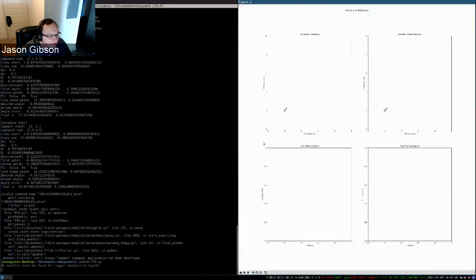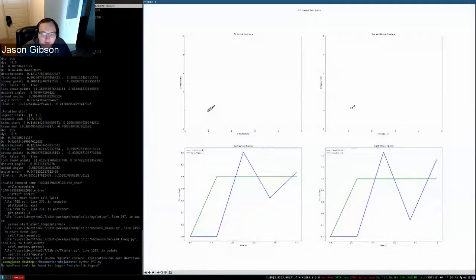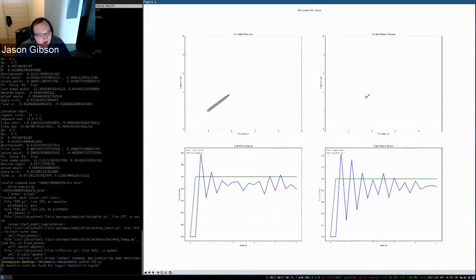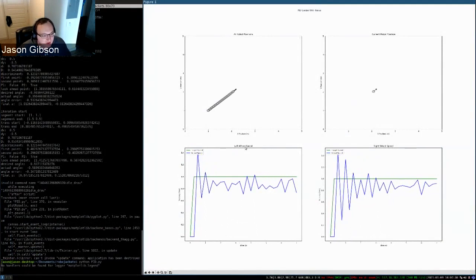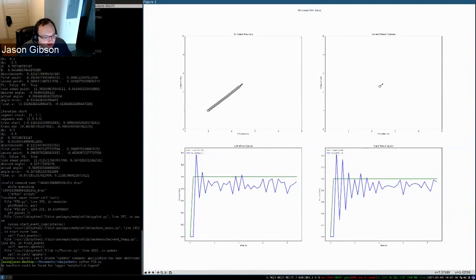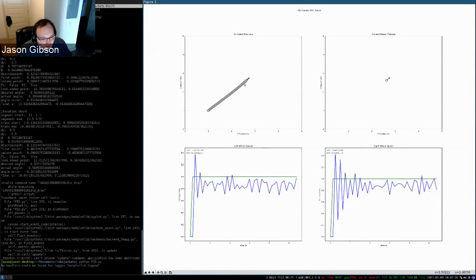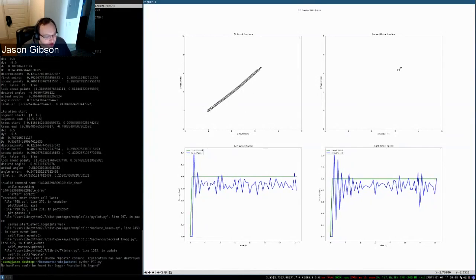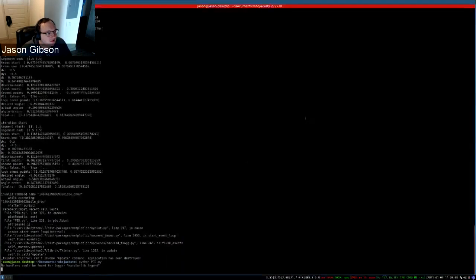We're going to get probably a pretty good P here. Now you're seeing more of the standard P behavior, but you still have oscillation because of the noise. And you can see how even with just P, compared to previously open loop control, we're driving in a significantly more straight line, which is usually what you guys are looking for when you're doing control.